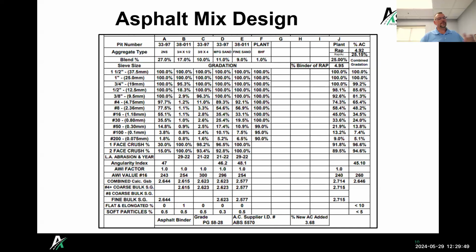Yeah. So if you get this mix design submitted from a contractor, a producer, for a certain job, and it's this 1931 form, this has all the information on it that you know has been tested and checked. So you really got to check that against the specifications. If you're using the MDOT specifications, you go to the MDOT tables. There's multiple tables: tables for the volumetrics for the mix, and tables for the aggregates that you use. And you got to check that it meets all of those.